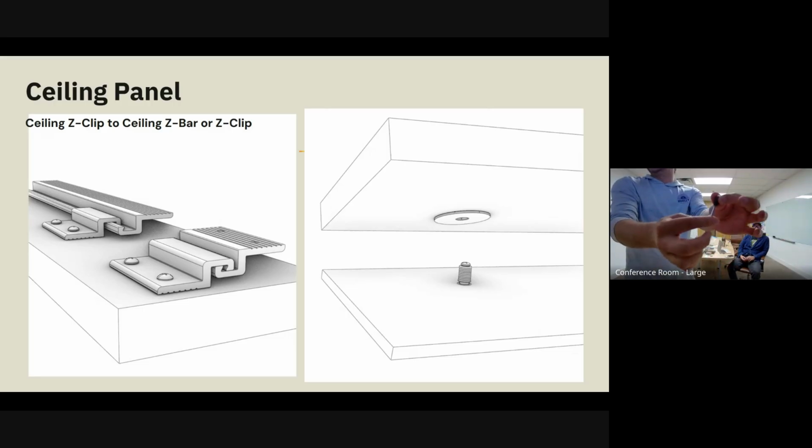And that's what gets screwed into either the wall or the ceiling. And that snaps in where the lollipop would go. This is a very permanent solution. So if they need the panels to be removed, this is not removable. This is not the solution for you. You will destroy either the panel or the wall trying to remove this hardware.